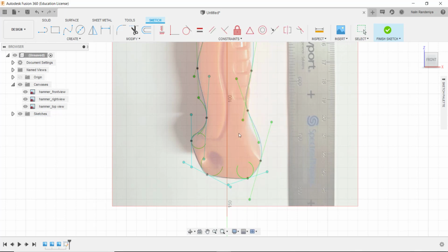Click on that. Now you can see a cross in the mouse pointer. When you touch the spline, find the place you want to add a point and click. There you go. That is the new spline fit point, and it has the control features if you want to control the curvature.